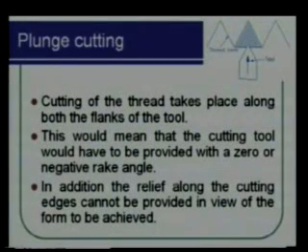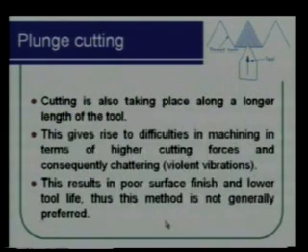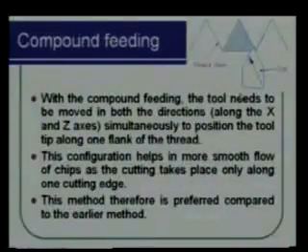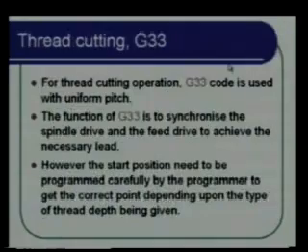Yeah, in plunge cutting, thread cutting takes place along both the flanks. Therefore, this would mean that the cutting tool would have to be provided with a 0 or a negative rake angle. In addition, the relief along the cutting edges cannot be provided. So that results in poor surface finish and lower tool life, and generally it is not preferred. Okay, when it is going along the flank, this will help in a more smooth flow of chips, and therefore generally this is a much preferred form of feeding.